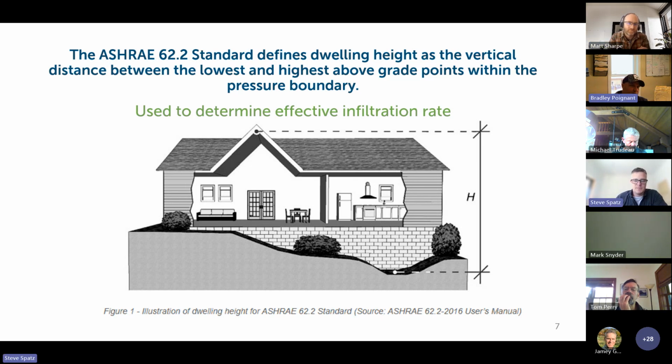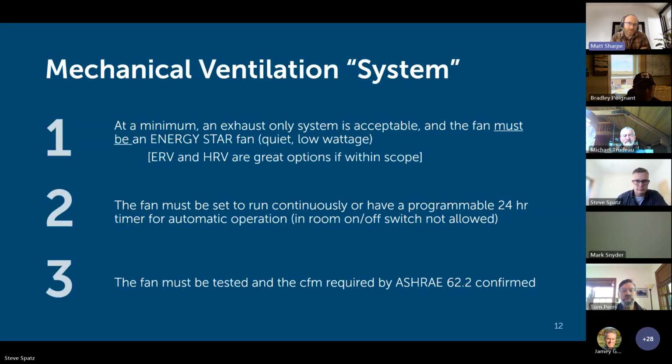With this picture right here, would you say the cathedral is insulated to the peak, but then you insulated the attic flat continuously down? Do you think average that out or no? You mean have two thermal boundaries? No, it's like that. The cathedral's slopes are insulated, but then it connects to an attic flat at the highest point, bottom right there. Yeah, highest point. So just the highest point. Okay, you don't average. Right. Yep. It's really to determine stack effect. So that's why it's the highest and the lowest point.